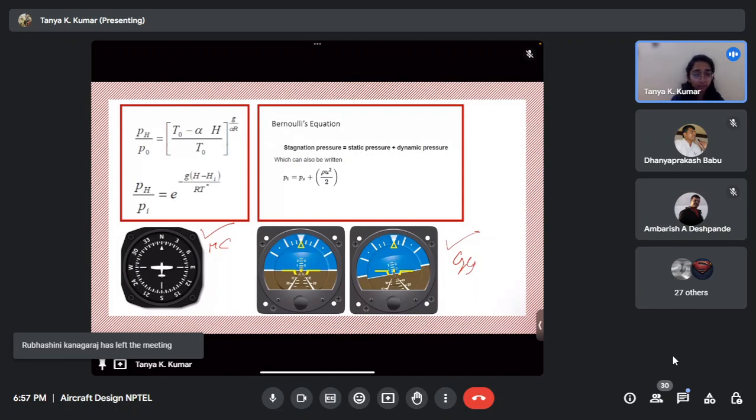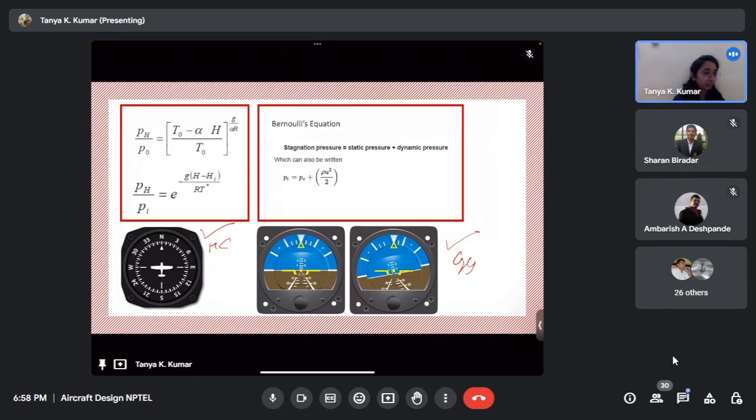Just try to think about it. So if I am flying, let's just take the longitudinal case. I am flying in a steady level and I am encountering a gust and it deviates from my equilibrium point. So if the aircraft tends to come back to equilibrium, I am telling that it's a statically stable aircraft. Okay, so what structure on the aircraft brings it back? What component of the aircraft brings it back?